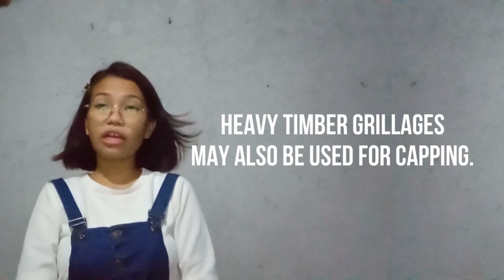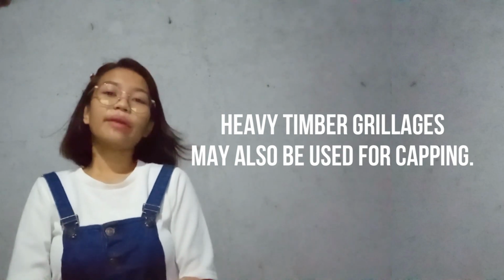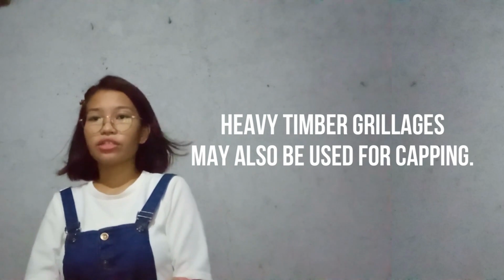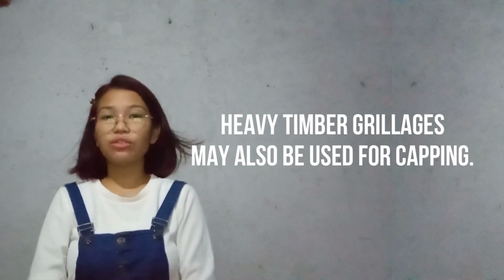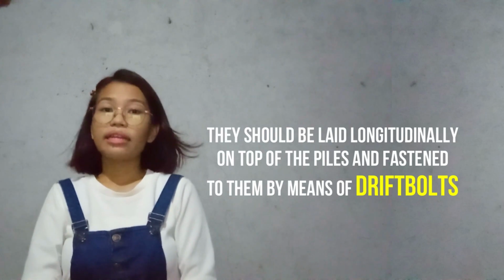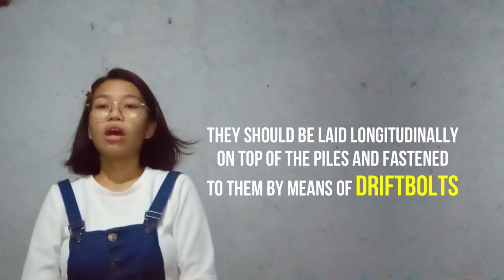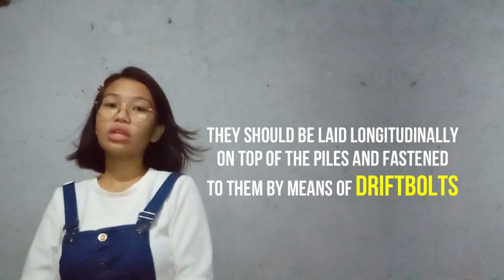The timber for the grillages should be at least 10 by 10 inches in cross section and should have sufficient transverse strength to sustain the load from center to center of piles. They should be laid longitudinally on top of the piles and fastened to them by means of drift bolts.